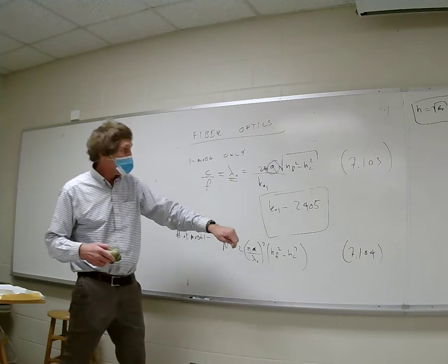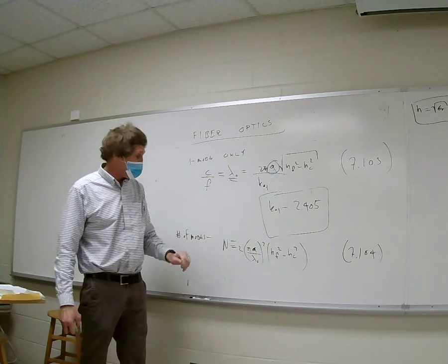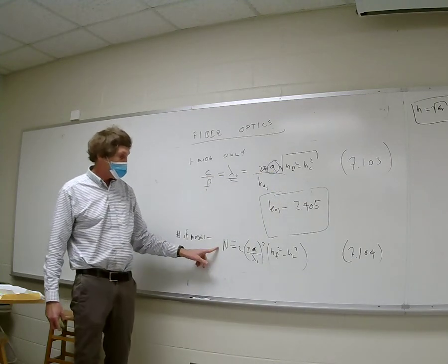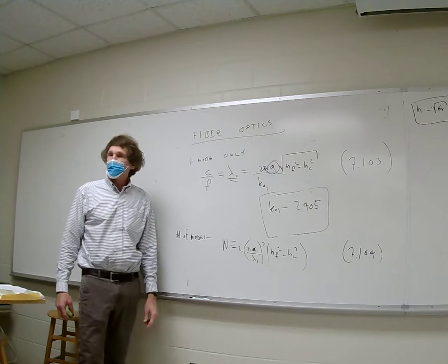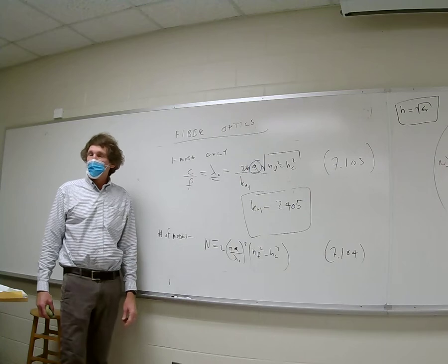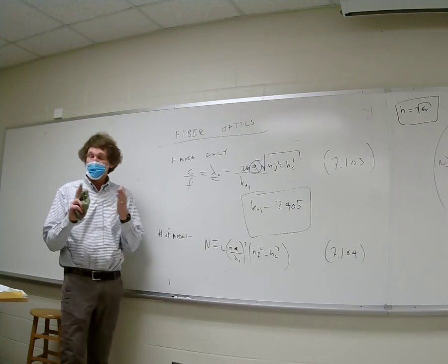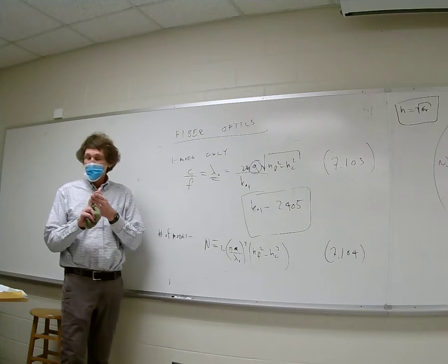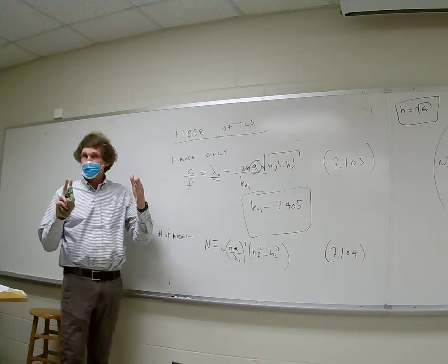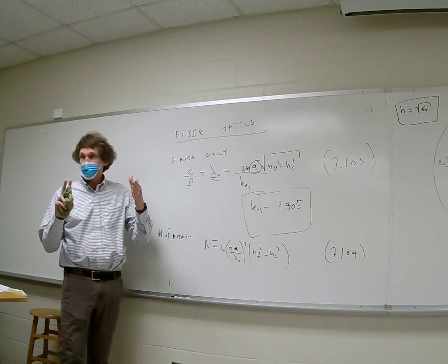Remember this. This right here is the key design parameter for single mode, and this is the number of modes. Now, why do you need the number of modes? If you're sending a packet of information, remember, the greater the number of modes, the greater the rate of dispersion of the pulse. We don't have the formulas for this in the book. The faster it broadens, the less far you can use it.